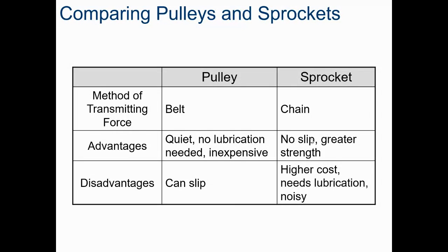It costs more. It's metal, so it's got to be greased. If you don't keep it greased, it's going to get rusty and lock up, maybe, if you don't do good maintenance on it. So it's got some good points and some bad points. We use chain on our first robot quite a bit for different reasons. Main thing being just because it is a fairly reliable way to provide power. And it is adjustable. That's one thing that is pretty nice about sprocket and chain systems.